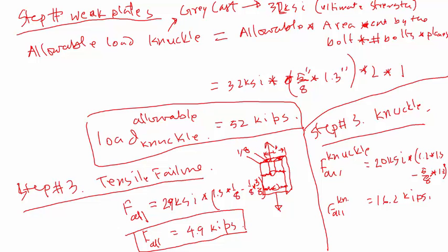So to review, your answer will be the lowest number for these connections. If somebody asks you what is the maximum this connection can take, you can say about 5,000 pounds, because it's going to fail if it goes under tensile load. However, remember this might see different types of loading, so you should always point out that under tensile loading it can take a maximum of 5,000 pounds.